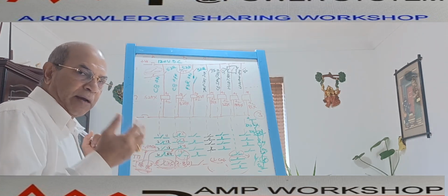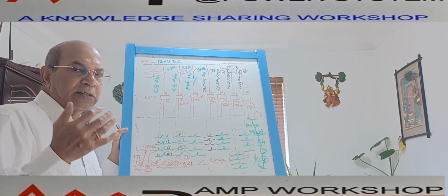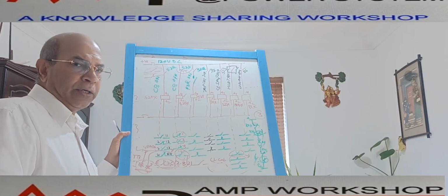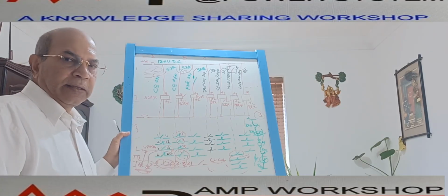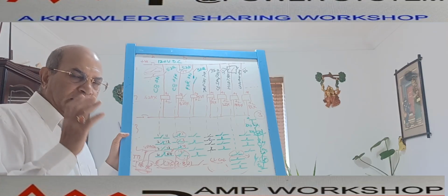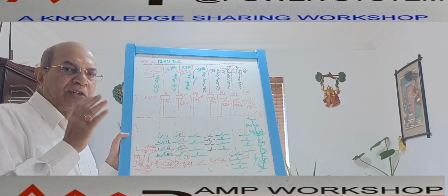In the case of medium voltage or low voltage circuit breaker, there is a service, test, isolated position. Now, circuit breaker on does not mean that the power is flowing through the circuit breaker, because the service breaker can be closed in the service position as well as in the test position.